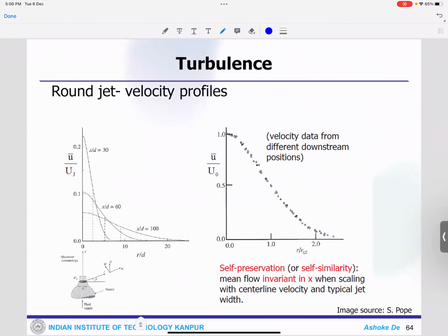These are there in the classical books. So this looks like that. This is how the jet comes out. If you see that example, as you go along the downstream direction, initially you have a much higher velocity, and slowly because of this energy transfer process the velocity also reduces. Where is this flow getting energy? It is getting energy from the mean flow field. So when the turbulent energy picks up, the mean flow is also getting reduced because it has to lose the energy. Ideally, the energy has to be conserved.